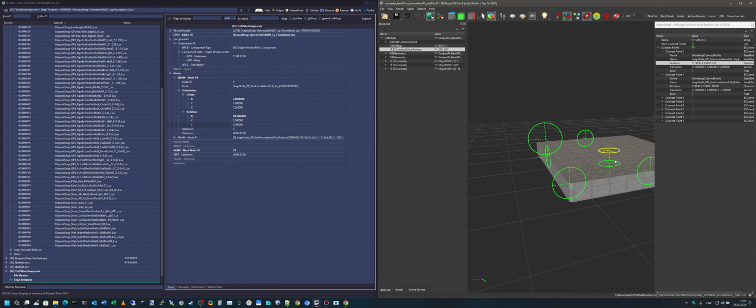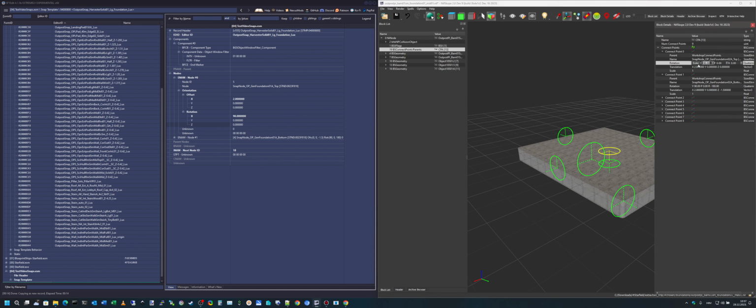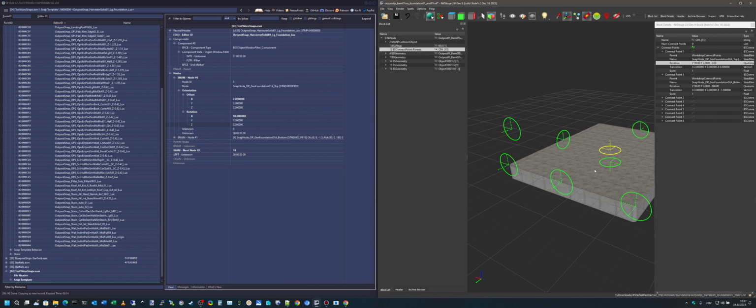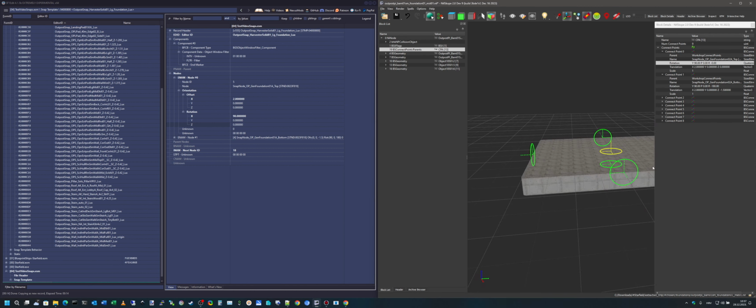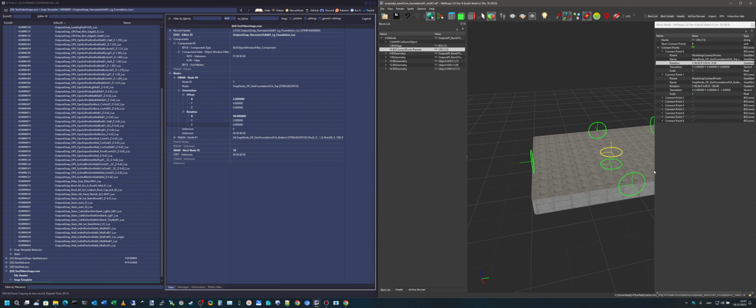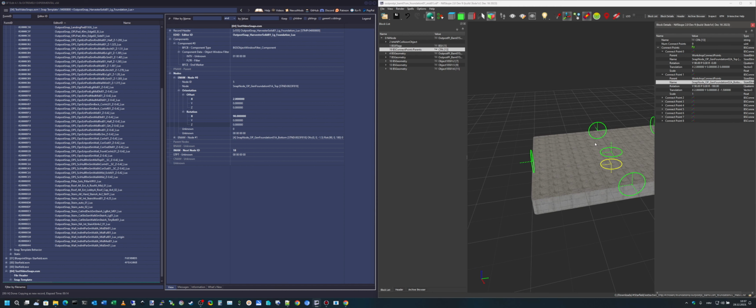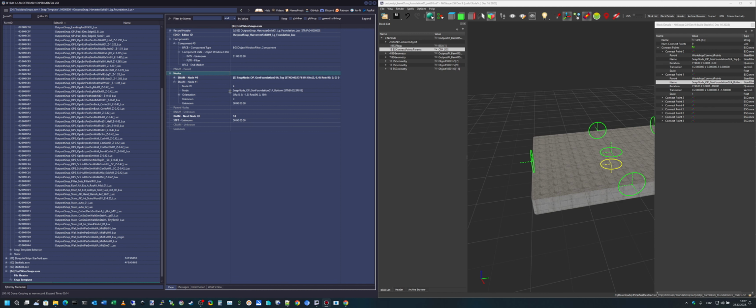You will see that this pointer is now pointing inside the model. You want this at 90. So only 0 and 180 are interchangeable with negative values, but other values have to use the correct prefix. So next one is the bottom node. So we are actually finished with this one. So it's top node. And then you have to change the bottom node.